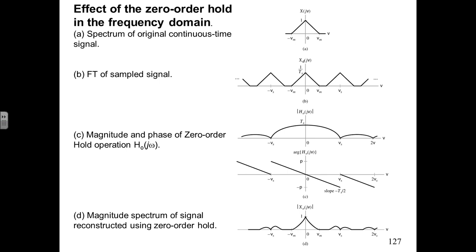So graphically, to see how a signal processed with a sample and hold reconstruction would look, at the top of this diagram we have an analog signal whose continuous spectrum looks as shown. And when we sample it, we get the second line where we get all the spectral copies. Now, again, we would prefer to use an ideal low-pass filter to pick out just the center triangle.